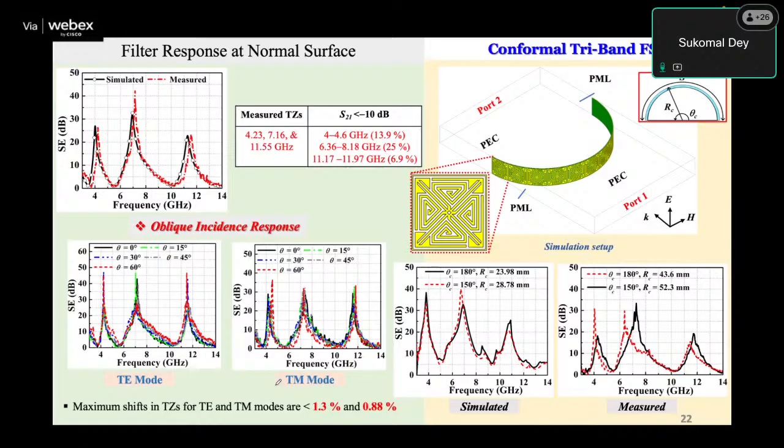If you are using a transmissive FSS, look at whether it is band pass or band stop. Why is it like that? In the band stop response, you are considering what? Transmission zeros, right? Yes, sir. You have to use that for your calculations.